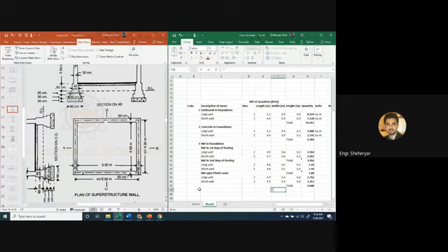If I write it, so these are the total brickwork quantities in the first step of footing, 3.456 cubic meters. Then in the second step of footing, this is 2.88 cubic meters. And then in the third step of footing, this is 4.608 cubic meters. And note the units.